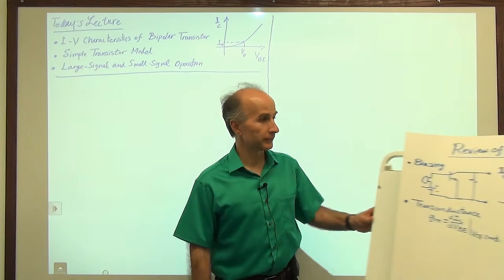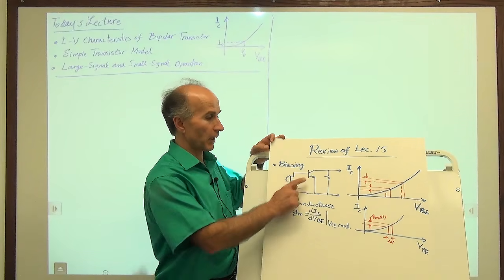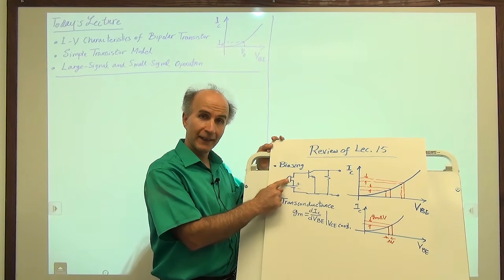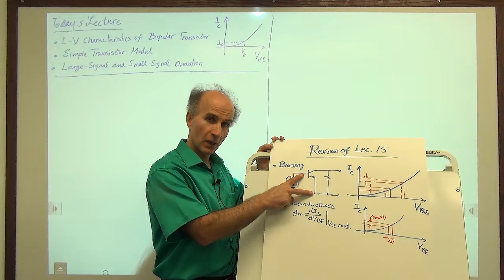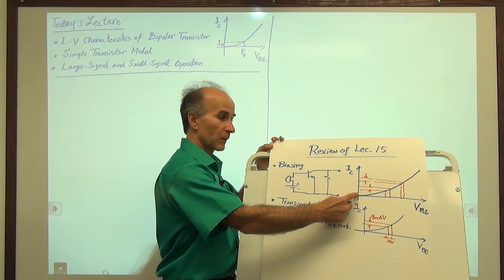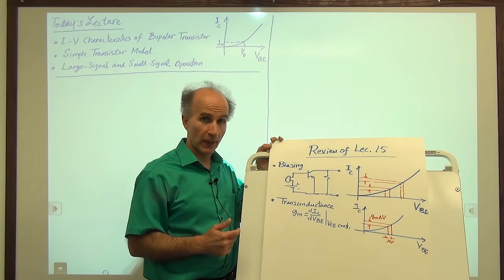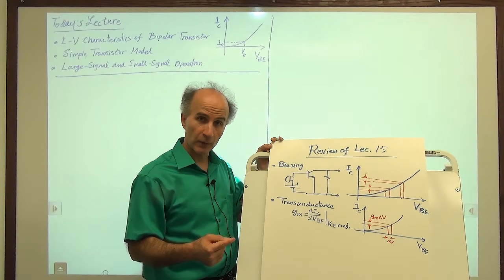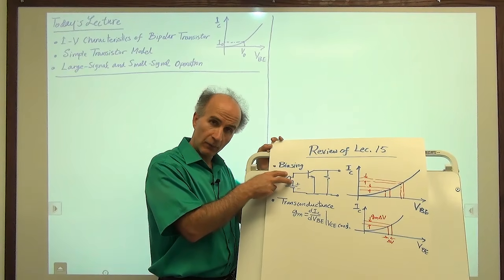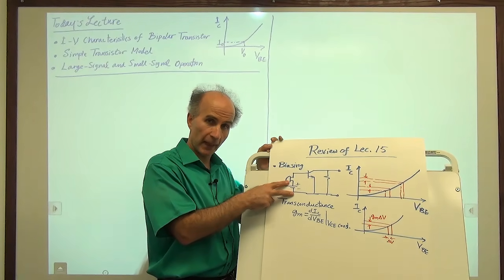In the previous lecture, we tried to build a little amplifier using a bipolar transistor, and we noticed that if we apply the microphone signal directly to the base emitter voltage, then the current that we generate is extremely small because we are over here in the IV characteristic. That's not very good, so we played a trick. We said, what if we superimpose this microphone voltage on a DC value that is provided by a battery?